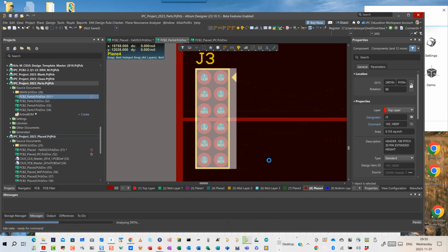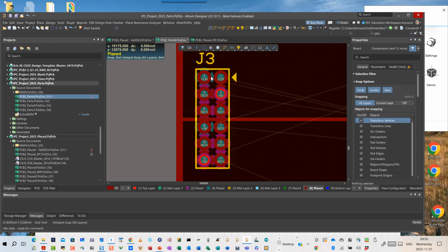And if I put that connector right there like that, you'll notice because I have those layers defined and I have a plated through hole, 3.3 volt is directly connected to its plane. So you can see the different colors of the thermal ties right there. D return connected, 5 volt connected here, minus 15 connected here, A return connected here, plus 15 connected here, and so on. So anytime I have a plated through hole that needs to connect to a layer that's defined on one of these planes, I simply place the plated through hole and the tool will make the connection for me according to the rules we created last week. Okay. So that's how we're going to do our plane definitions.